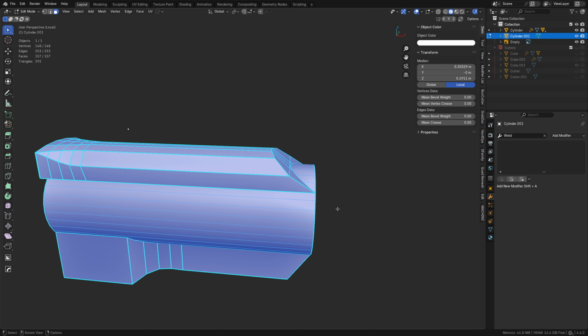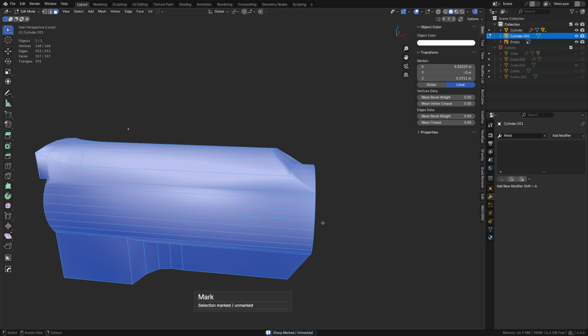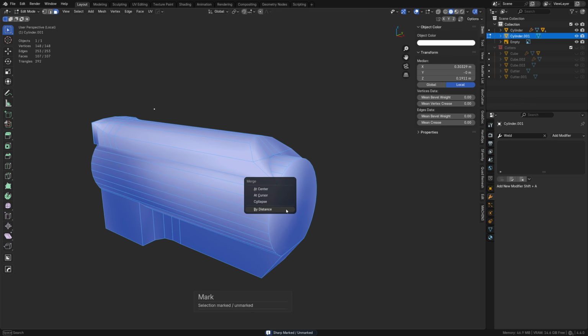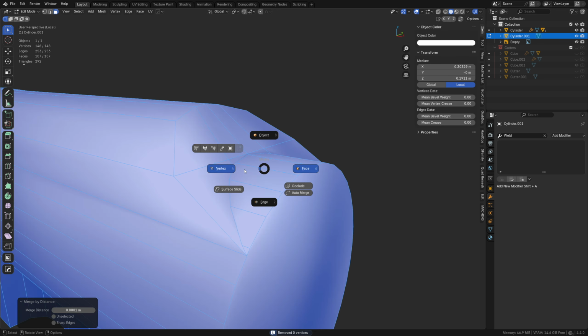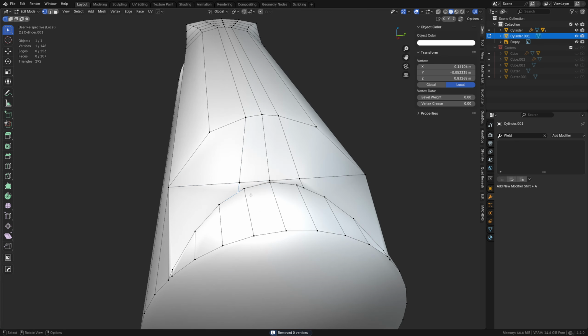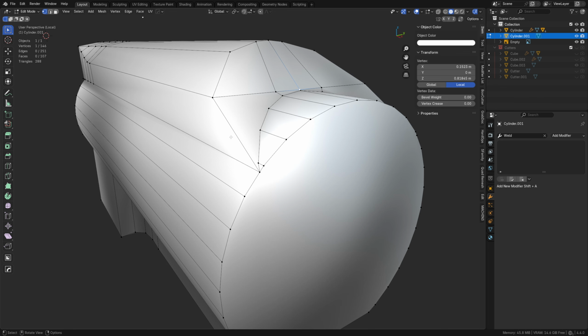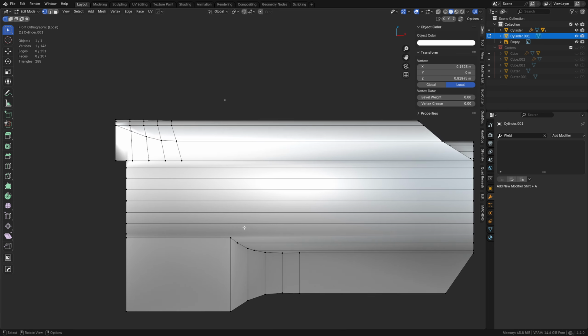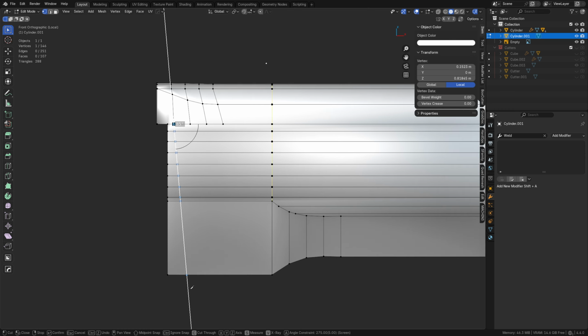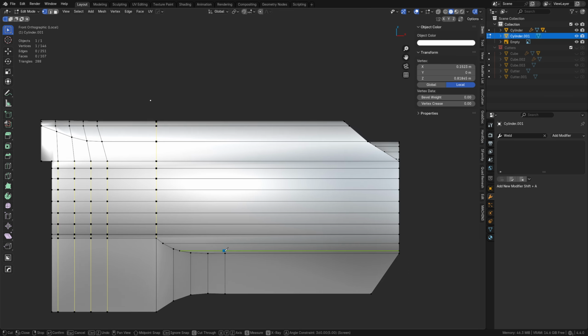It's like block out, then subdivision. So a lot of people say, don't use booleans, and then they don't have any idea what they're talking about, because you want to use booleans if you can. And then if you need to clean things up and make them nicer, you see where we're going with this? We can do that. So we have a lot of little things we got to work out here possibly, but the best way to do this is converting big n-gons into quads. So use a knife tool, start cutting out what makes sense the most in kind of the right directions, and just start going from there. It's easier to sometimes quad things out than doing holding edges first.